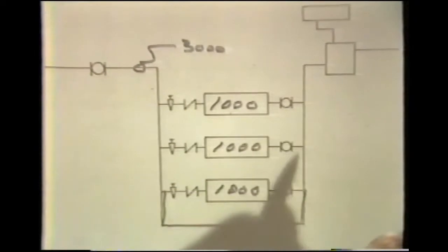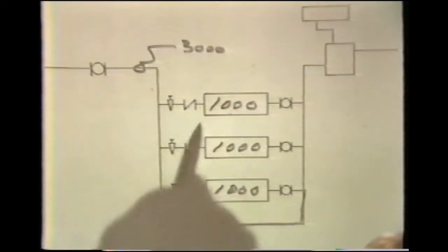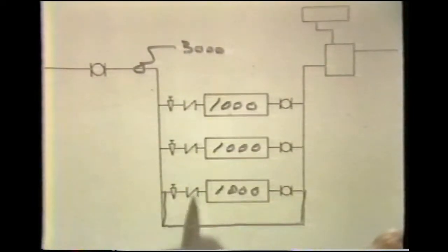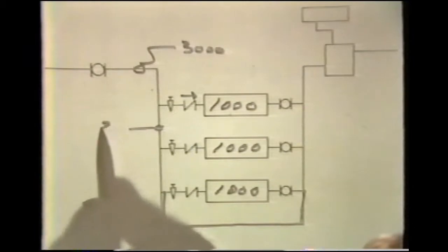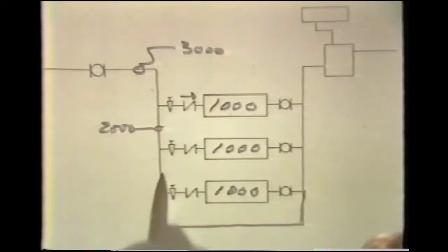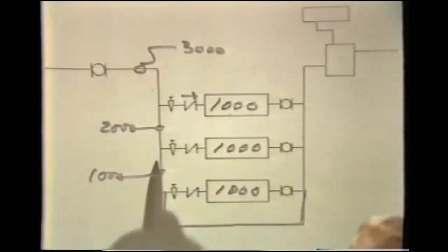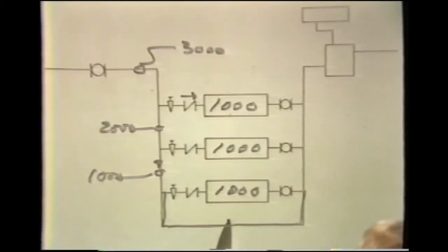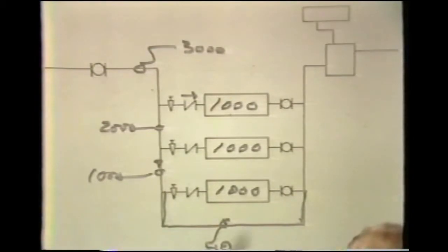Now, this would mean that each chiller is developing 1,000 GPM flow rate draw. So we'd have 2,000 at this point, 1,000 flowing through that segment of the piping, and we would have zero flow in the last, or the common piping section of this illustration.